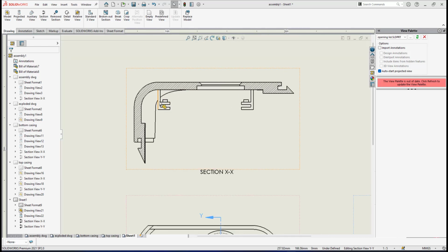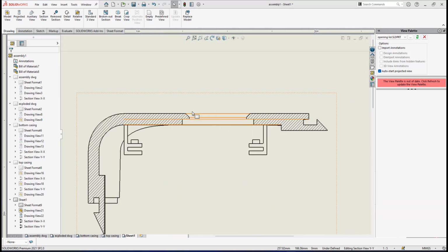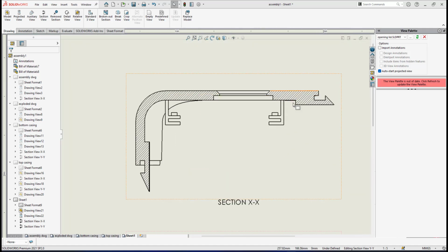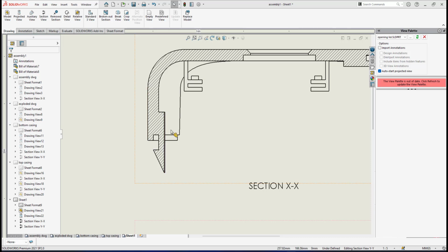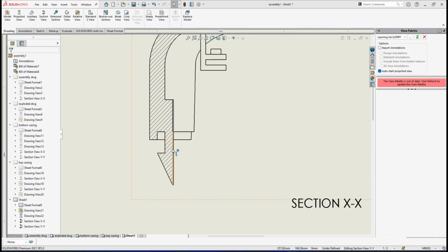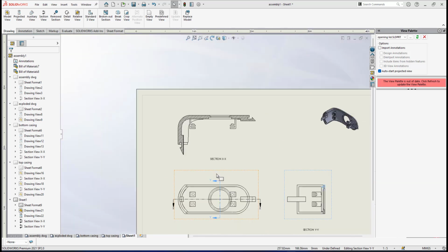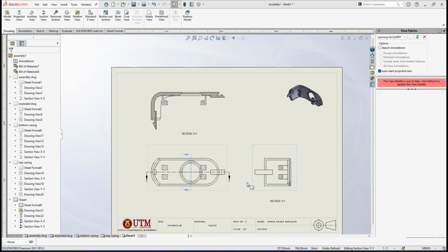For example, the dimension of this arm, we have a slot here. And also the dimension of this push button, we have a cutout here for the push button to be mounted onto, and the holes here. And also we need to put dimension in terms of the thickness of this opening lid. What is the main thickness? It's 1.5 thickness. And also dimension for these two hooks here. I have hooks here for the snap hook features, and also I have the hooks here. So you don't have to put really detail, just the important features that we can show for this detailed drawing.